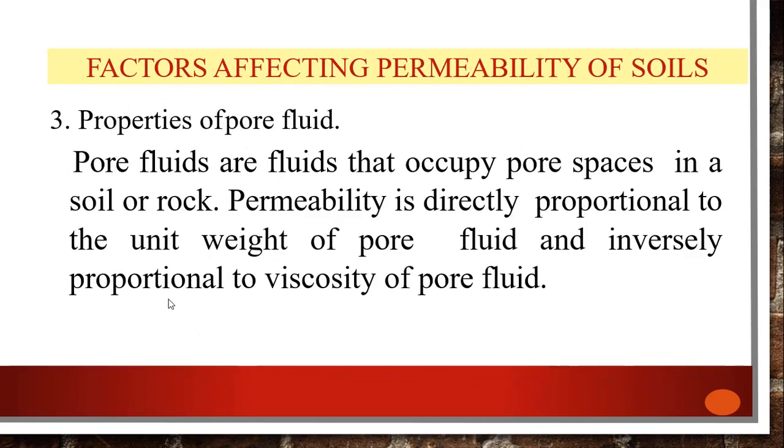After that, the properties of the pore fluid. Pore fluids are the fluids that occupy the pore spaces in a soil or rock. Permeability is directly proportional to the unit weight of the pore fluid and inversely proportional to the viscosity of the pore fluid. If the viscosity of a fluid is high, the permeability will be very low. A viscous fluid means a fluid which is sticky in nature. In that condition, the fluid will not flow easily from one region to another because it is very sticky, so the permeability is very low.